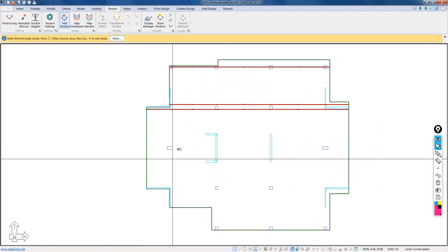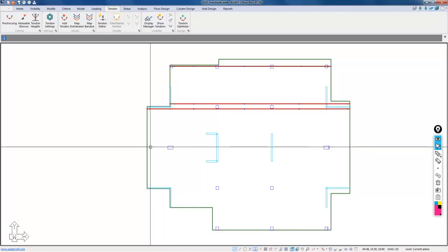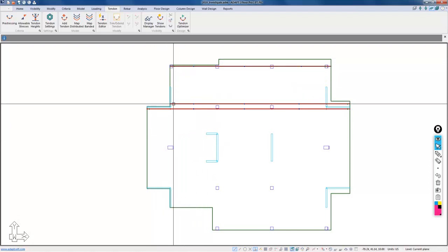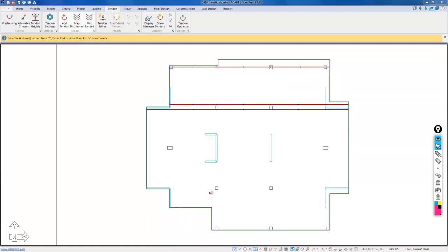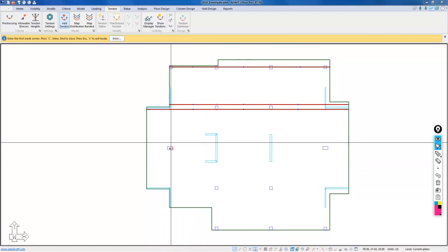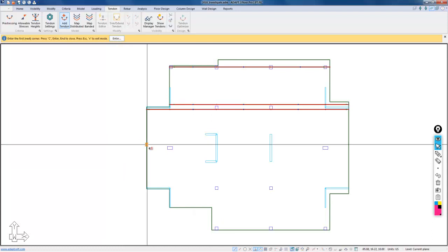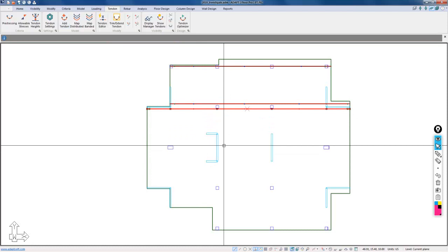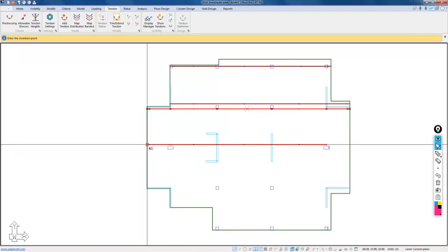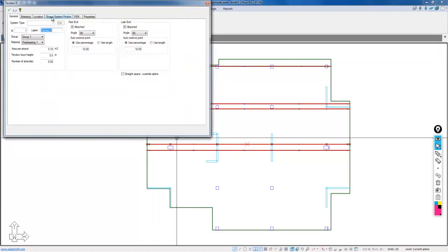let's see, actually before we do that, let's model one more. This is almost a dummy tendon, but in this case we need it to reference the distributed because we said we were going to anchor the distributed behind it. So let's add one more set of banded tendons here, and these will also be 8 strands. So I'm going to go back and actually we're just going to copy this one. Control C, Control V. I'm going to say 1 and 2. And all we need to do here really, they're already set to 8.